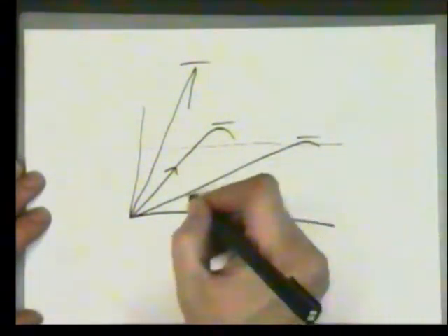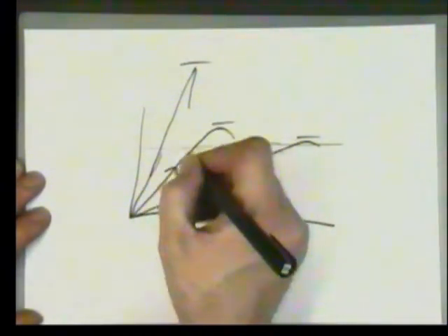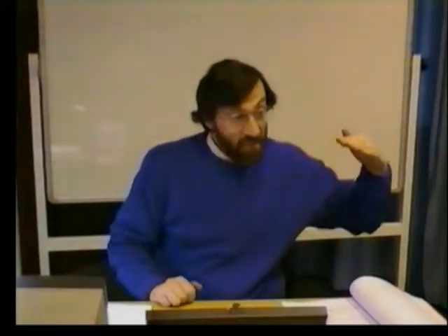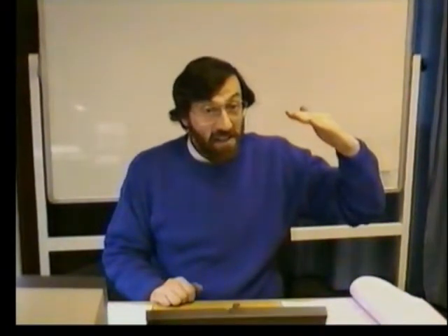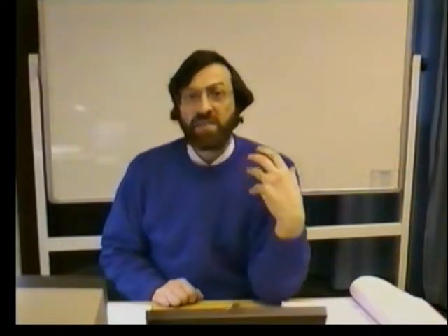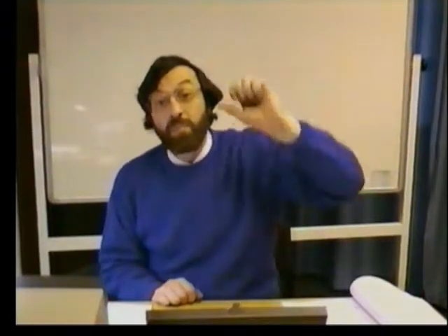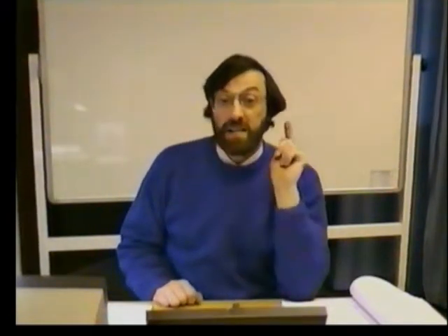So if we could predict we're shooting up too fast and slow us down, then we might have a way of bringing the integral term under control before it's done any damage. So what we're saying is that we're rising to the set point, and if we see we're going far too fast, we predict in advance there's going to be a problem, and rather than have to click in one of these very harsh resets or clamps, we slow it down before the damage occurs. And it's much better to predict there's going to be a problem and stop it happening than to let it happen.